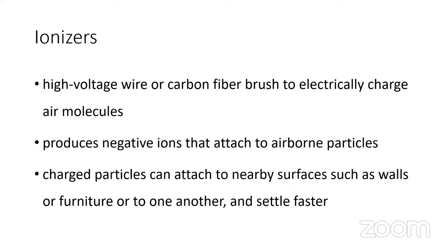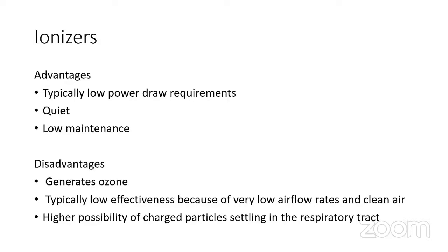The clean air delivery rate would be much less when compared to the other cleaning mechanisms. So for ionizers, you have advantages like the power requirement is low. They are very quiet and low maintenance, because there is no fan. There would not be any possibility of noise. And disadvantages are normally that it generates ozone in the process of charging, and low effectiveness because of the low CADR.